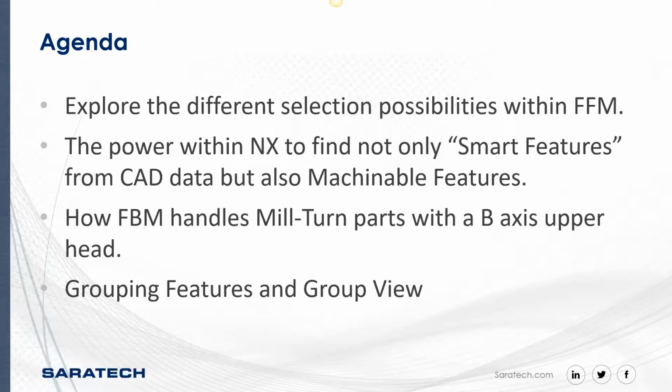If, say, you had a tapped hole, there are 3 different features: a chamfer, a cylinder, and then the tap. If you program that manually, you would have to select drilling or hole machining for your center drill and select the hole. Drill, select the hole. Tap, select the hole. By grouping your features together in the operation, in the dropdown, you don't have to leave it at work piece. You can actually use that feature group and it already selects those holes that you grouped together.